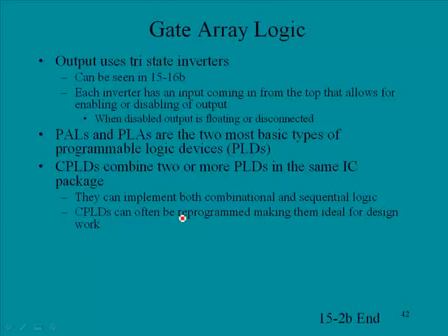PALs and PLAs are the most basic type of programmable logic devices. CPLDs combine 2 or more PLDs in the same IC package. The CPLDs can implement combinational logic, and they can do sequential logic as well. Many times, though not all of them, they can be reprogrammed, making them ideal for design work.